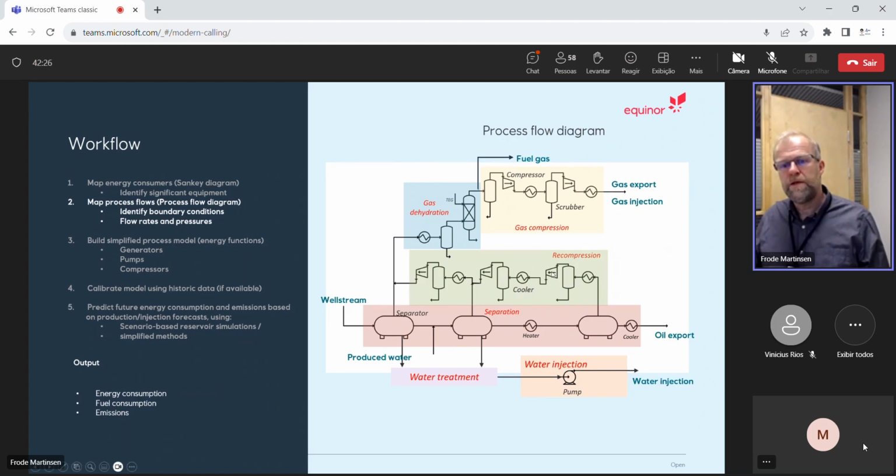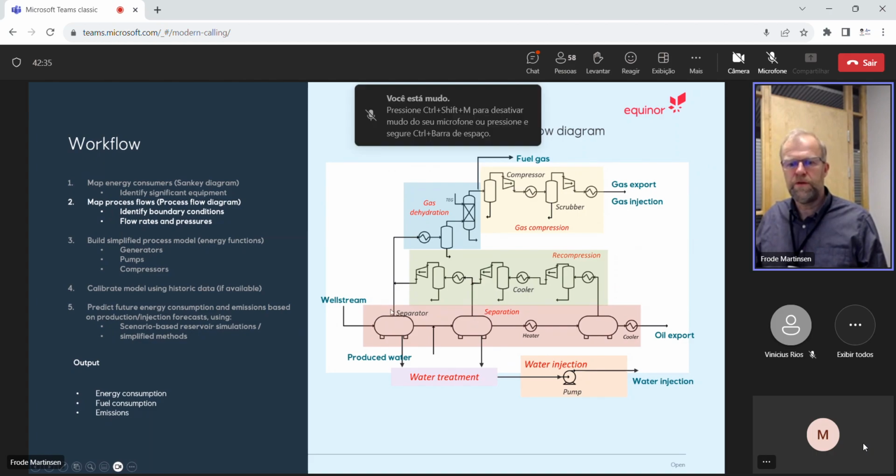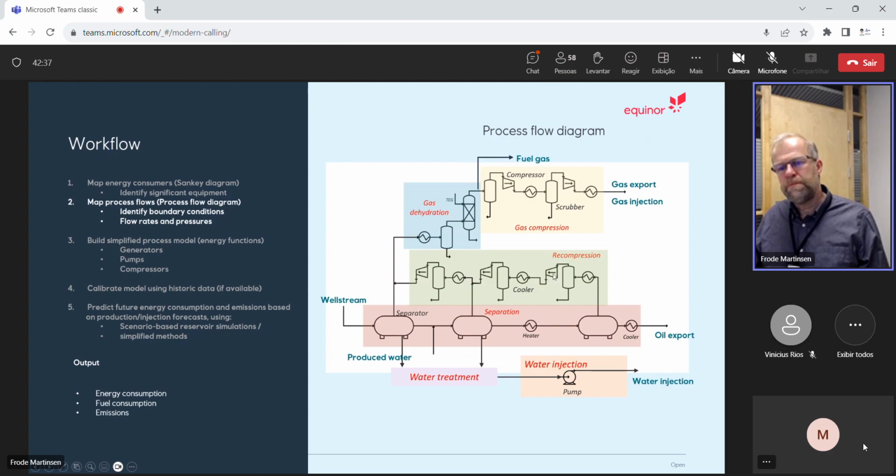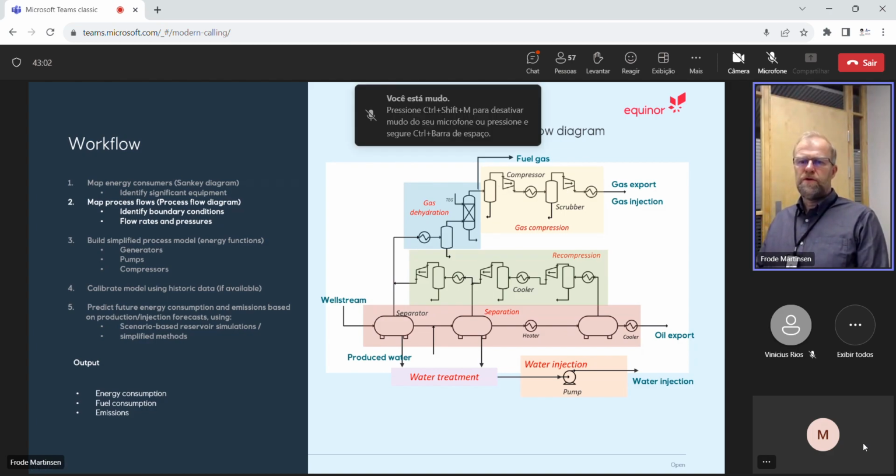Luckily, the energy consumption is low because the rate is low. For sure, the pressures are not varying. 1 bar, 7 bar, 15 bar throughout the lifetime. So it's at best a relation between rate and power. It's not pressure dependent. So by saying these are fixed or maybe only rate dependent, it's a fairly good approximation. But up here, these compressors we like to model. These are the ones that are typically turbine driven. These, the ones in the green, are typically electrically driven.